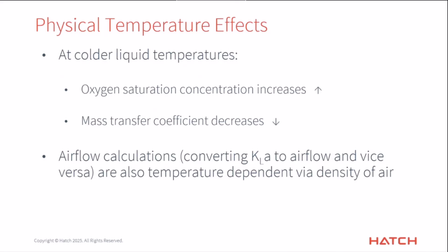Okay, so to summarize for our aeration system, at colder liquid temperatures, the oxygen saturation concentration goes up. So that means our driving force is increased. However, the mass transfer coefficient decreases with the colder temperature. Now, which one of these effects outweighs the other is a function of many things, but we'll see by playing around a little bit in our example.